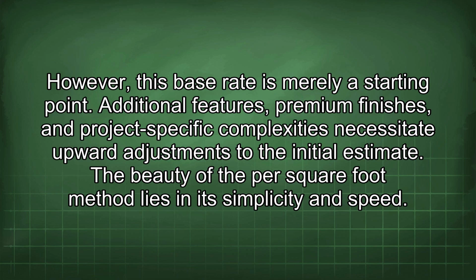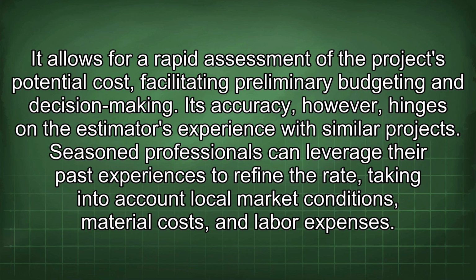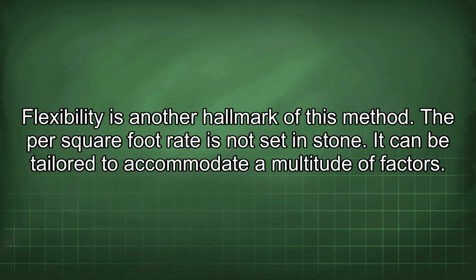However, this base rate is merely a starting point. Additional features, premium finishes, and project-specific complexities necessitate upward adjustments to the initial estimate. The beauty of the per square foot method lies in its simplicity and speed. It allows for a rapid assessment of the project's potential cost, facilitating preliminary budgeting and decision-making. Its accuracy, however, hinges on the estimator's experience with similar projects. Seasoned professionals can leverage their past experiences to refine the rate, taking into account local market conditions, material costs, and labor expenses.